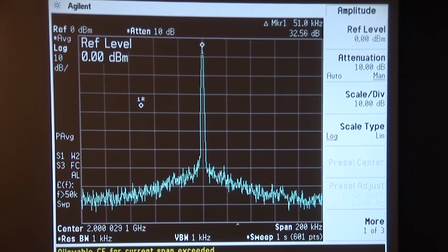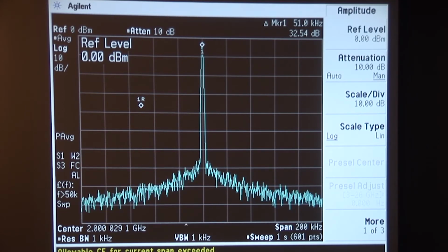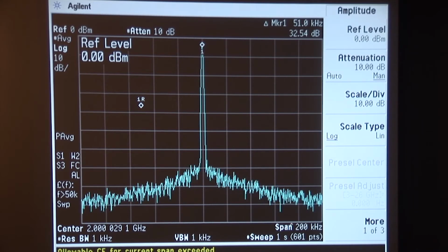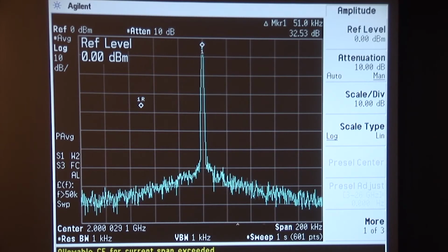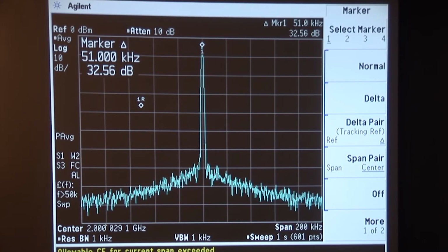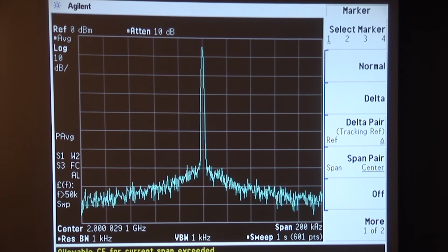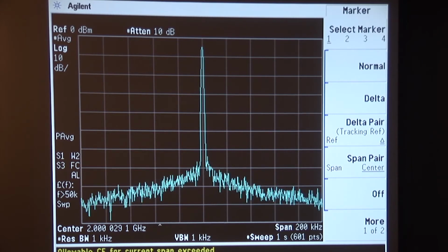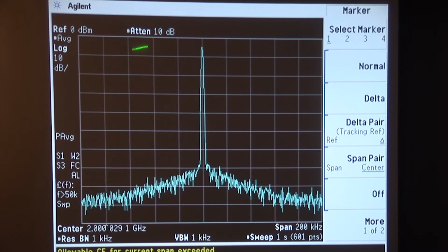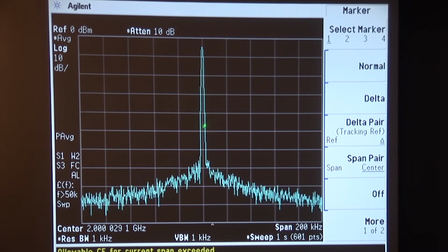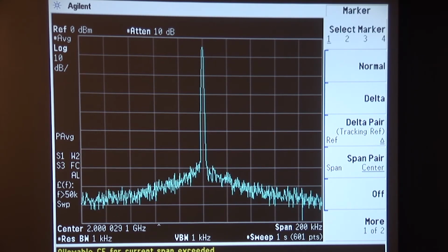So again, you have to consider the trade-offs when you're running a spectrum analyzer and you're looking at signals in terms of the sensitivity of the spectrum analyzer, the amount of dynamic range that you have, and the overload power point that the spectrum analyzer has. Usually we're able to effectively accommodate these factors, but we are limited here to a total dynamic range of about 85 dB on this particular spectrum analyzer display, measuring from here: 10, 20, 30, 40, 50, 60, 70, 85. That's all we're going to get.